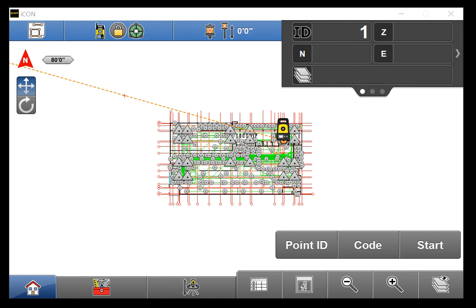Once these steps have been completed, we can use Move and Search to lock on the prism and begin storing information. Before doing so, we first need to define our understanding of as-built as it relates to survey software and the proper way to use this version of software. By definition, as-built drawings are a revised set of drawings submitted upon completion of a project or a particular job. They reflect all changes made in the specifications and working drawings during the construction process and show the exact dimensions, geometry, and location of all elements of the work completed under the contract.